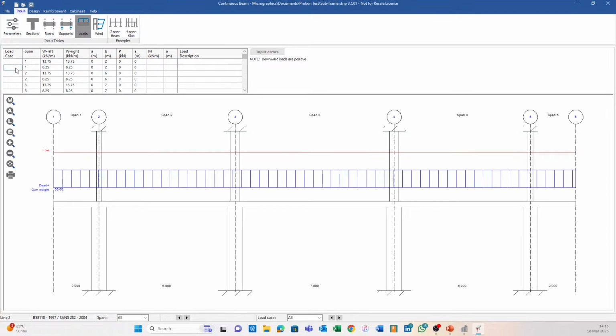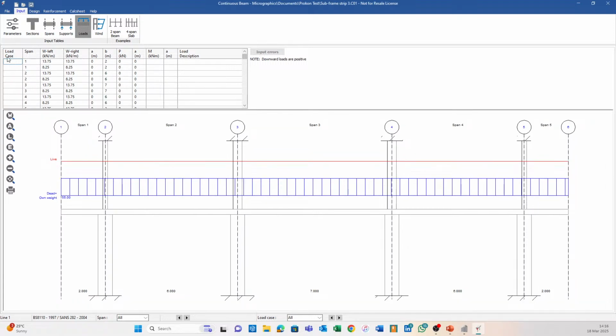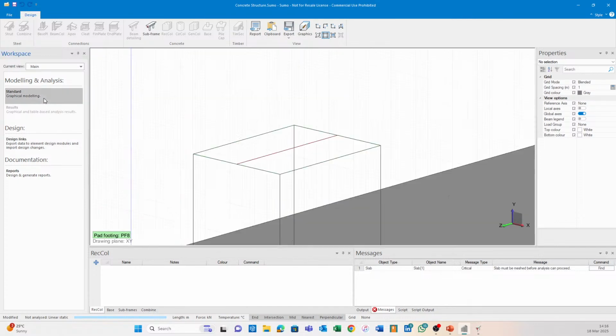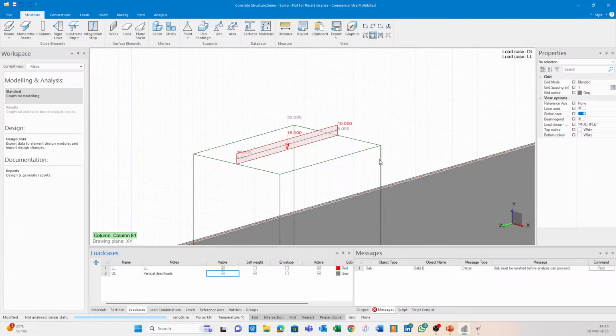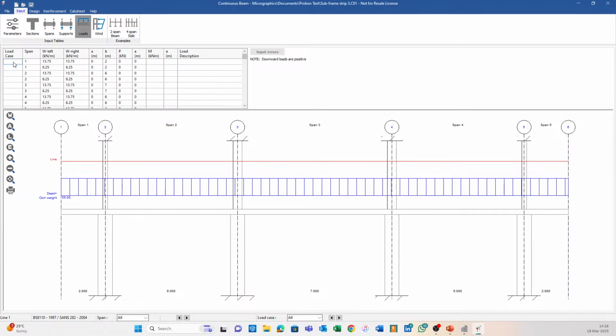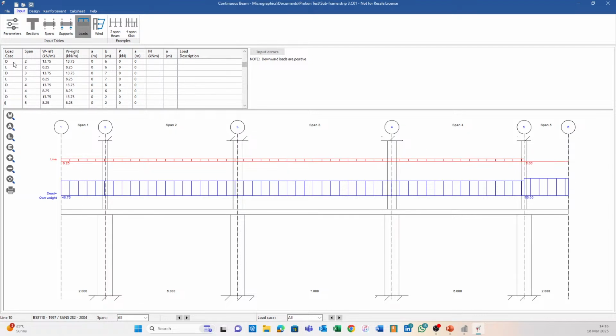The loads are pulled in as per what is within that net. And all that we must do is make sure that we assign a dead and a live load case to these different loads. So if I go back now and switch these load cases on again, I just want to see what is the magnitude of what. So the live load is smaller than the dead load, right? So we're going to start off with dead, live, dead, live, dead, live, dead, live.